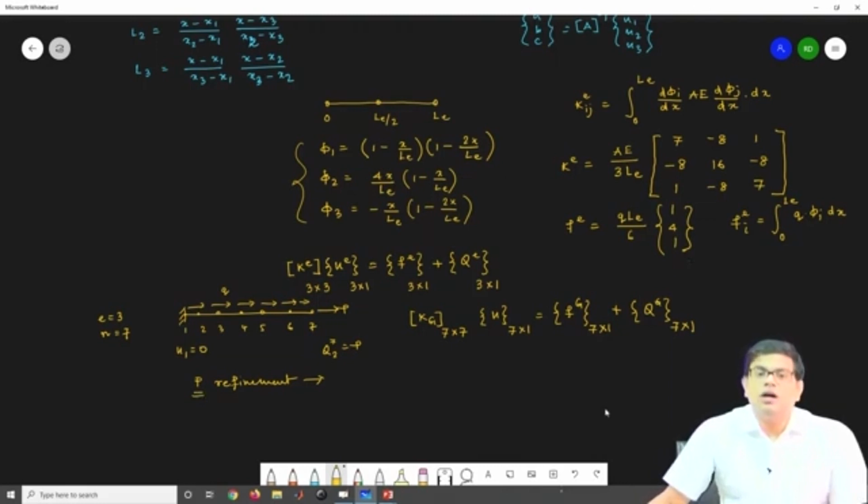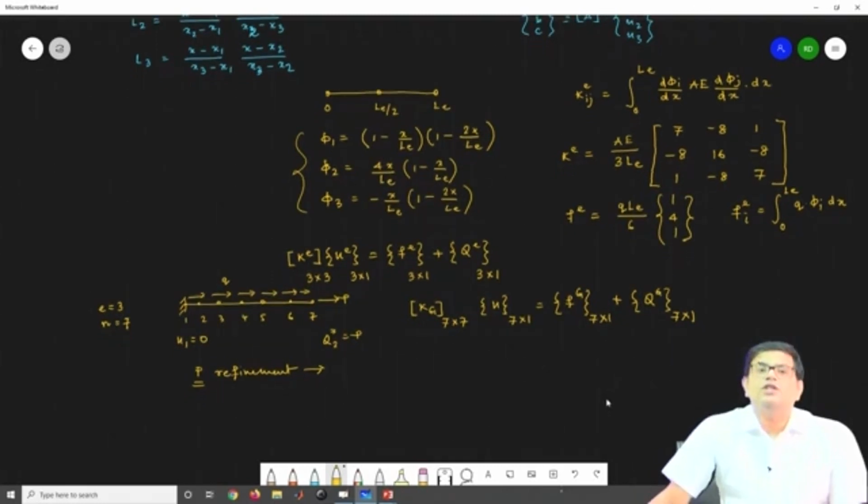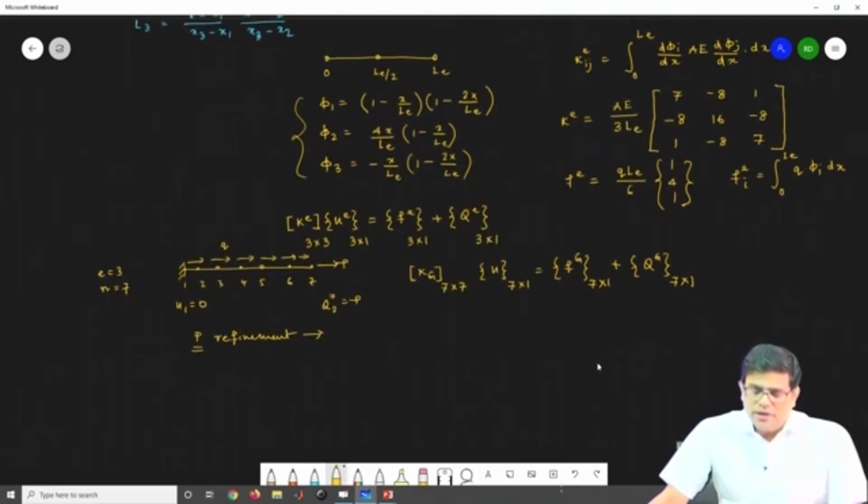So this is what quadratic shape functions are, and surely I can use it for a cubic element, and then a fourth order polynomial, so we'll have 5 nodes and so on. So that is the main issue. But as you increase the polynomial order, the Lagrange polynomial shows many phenomena like the Gibbs phenomenon and other things.